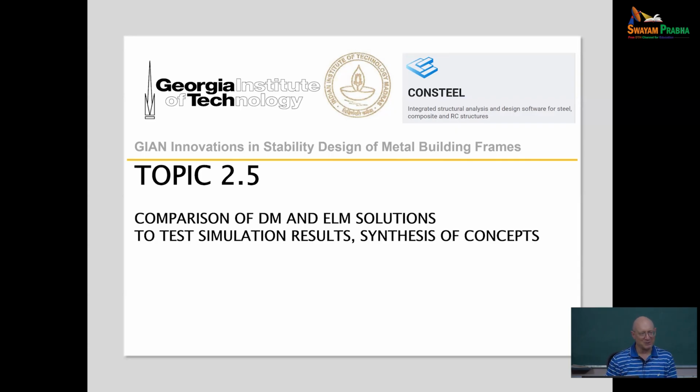So we have these differences in philosophies. My understanding of the Indian code is that it doesn't go there with any of those. It's really very close to what we'd say is an effective length method in terms of the overall solution. Is that correct? And then the checks with the column resistance and the beam resistance are very close to Eurocode.